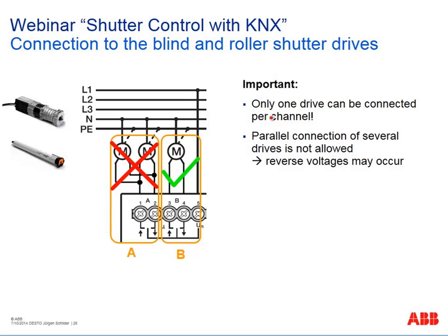Very often the question: can we connect more than 1 motor to 1 output? We can connect, but you should not do it. You see here the red cross on this part of the picture. If you connect 2 motors in parallel, you get problems. Not both drives run at the same time, so there are end position switches in such motors, and